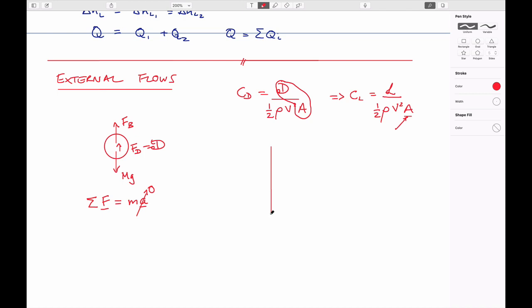And it comes back to a Moody-like plot, once again, of Reynolds number equal to density, velocity, and a length dimension by viscosity. And again, it divides between laminar and turbulent, and this is now a coefficient of drag or a coefficient of lift, which is also really an Euler number. And we have these two regimes.